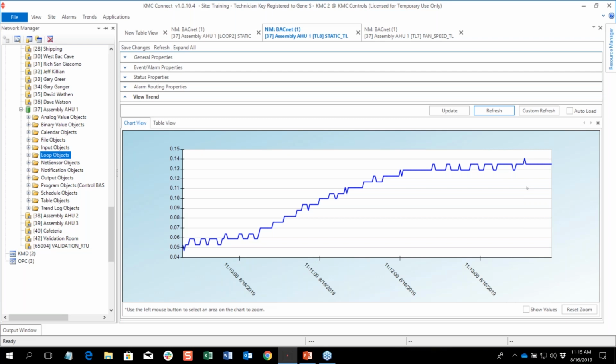Mm-hmm. As long as you do not introduce ringing, you're okay. So if I drive that I term harder and I do get ringing, would it be best to keep adjusting the I, or should I go back and adjust my P term to make that loop move quicker and then bring my I back in? That's what I would do. Okay. So there you've got two opinions, two different ways of doing it.